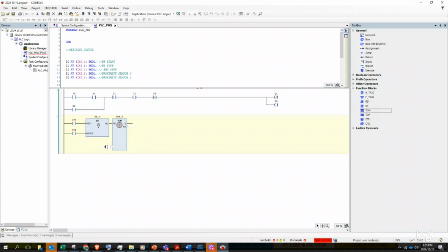We're setting this timer so that our cylinder can delay going forward, advancing. You can set it to however much you want. For this exercise, we'll just set it for 5 seconds. How you code that is you use the capital letter T, hashtag, and then the number of seconds you want to delay, and capital letter S, right? And then we are delaying advancement.